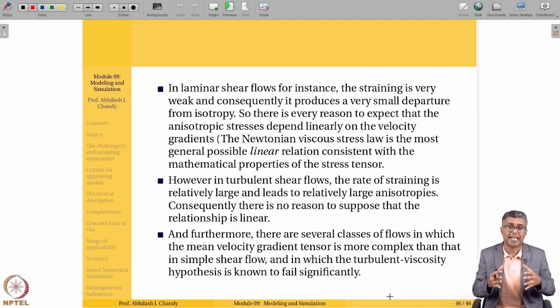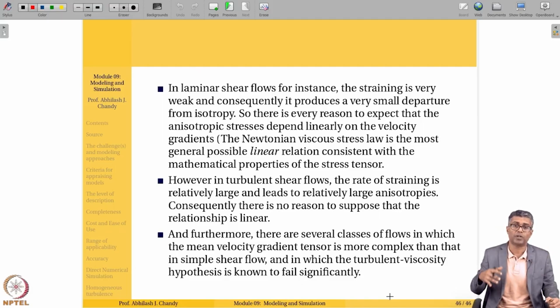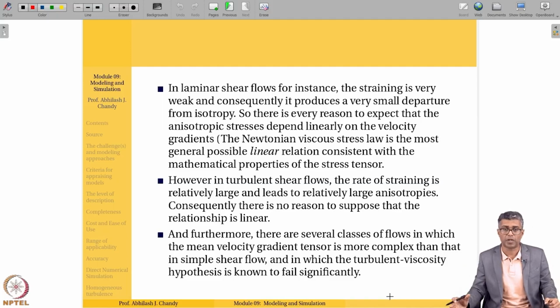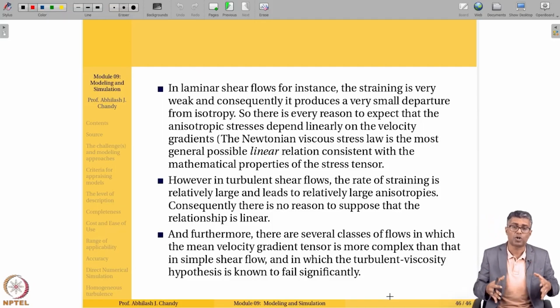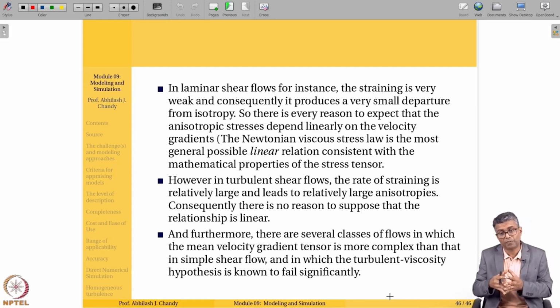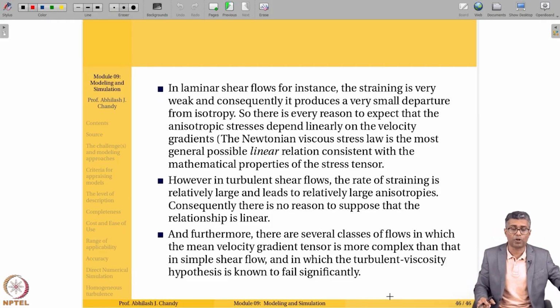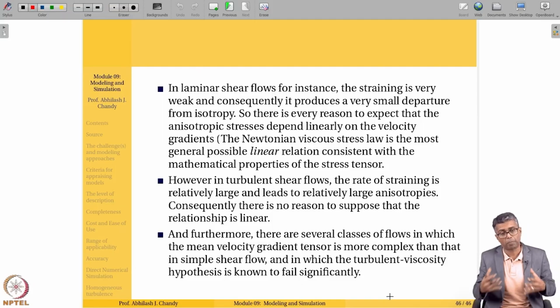Because so much cost is spent on resolving the scales in the dissipation range, we need alternative approaches like LES that spend most of their cost on the large scales. We also had some discussion on inhomogeneous flows, where simple periodic boundary conditions wouldn't apply and more complications arise, like wall boundary conditions.